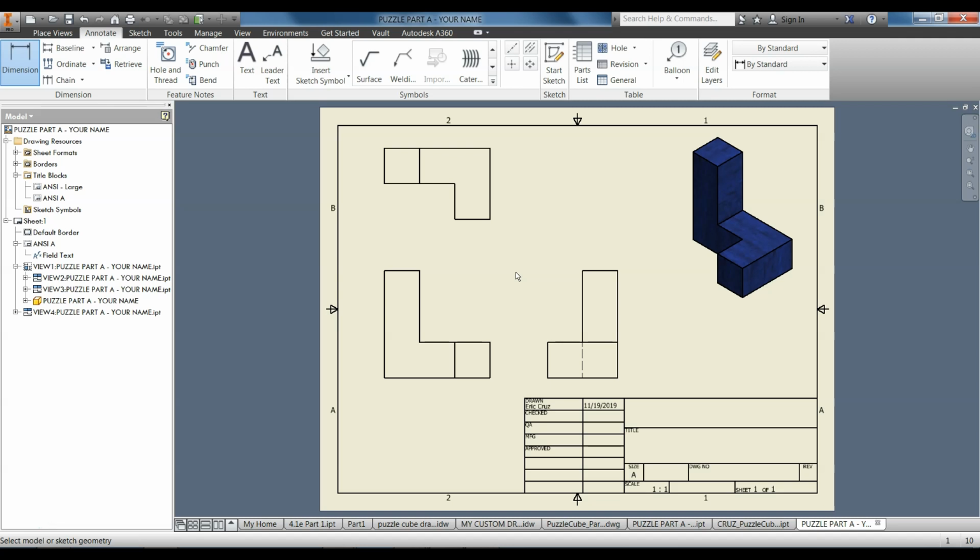Let's not think too hard about those rules right now, but the general basic rules of thumb are dimensions should never really ever be on the left sides of the part, here in between parts. They should never be very close to any other text boxes, and they should always try to be centered between parts.